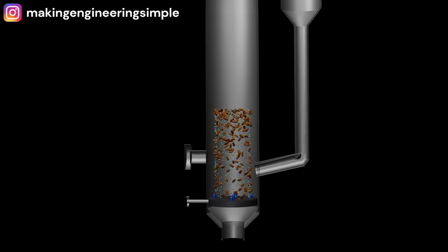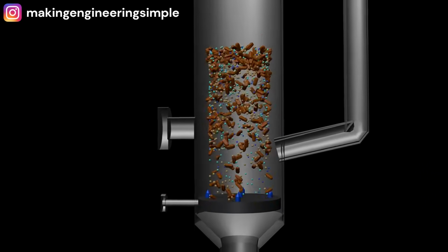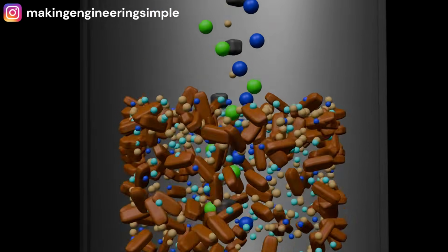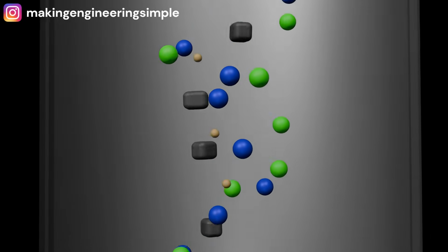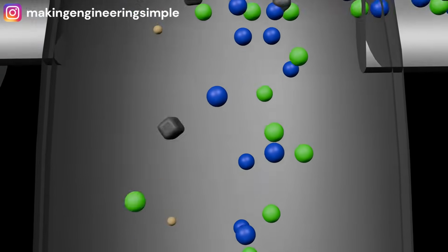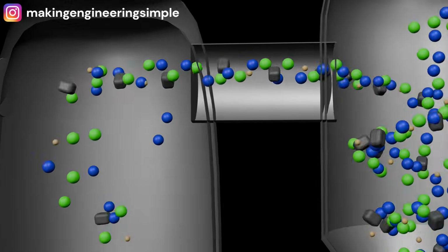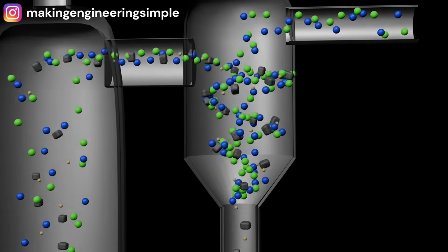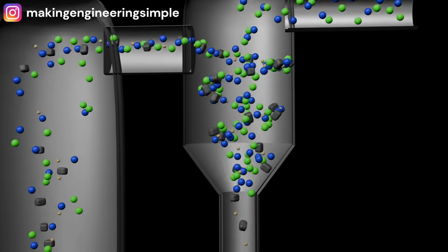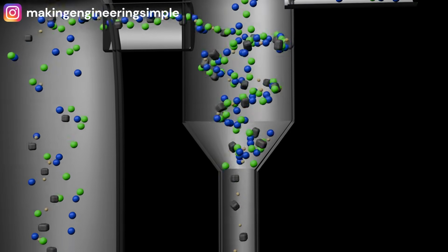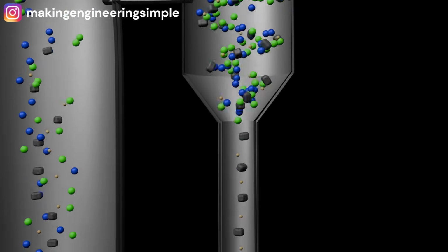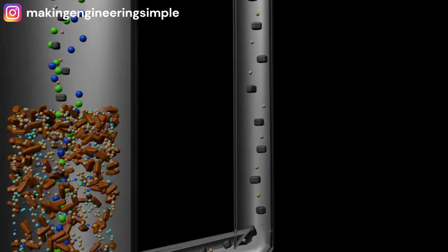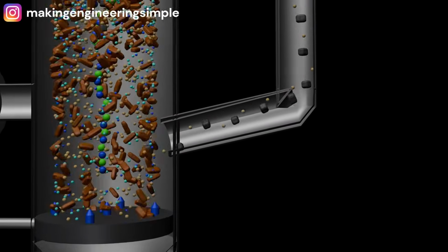As syngas is produced, some particles can become entrained within the gas stream. These particles must be recovered so that the overall efficiency of the process can be improved. This is achieved using a cyclone separator. The gas mixture flows upwards and out of the gasifier. The gas then enters the cyclone tangentially, and as the gas spirals downward, the heavier particles experience centrifugal force and are thrown outward toward the cyclone wall. The solids lose momentum and fall downward into the collection leg.